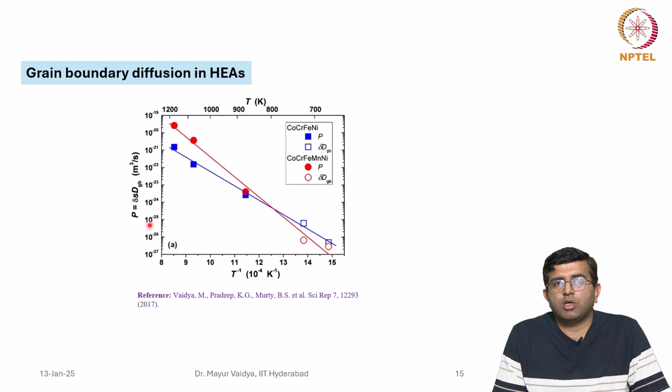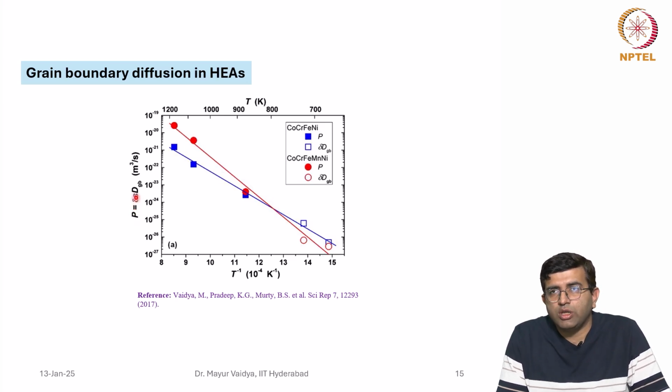When we talked about the grain boundary diffusion measurements, we also talked about the fact that in the B kinetic regime, for example, you can measure only the triple product, which is given by s delta dGB, whereas in the C kinetic regime you only get the dGB.